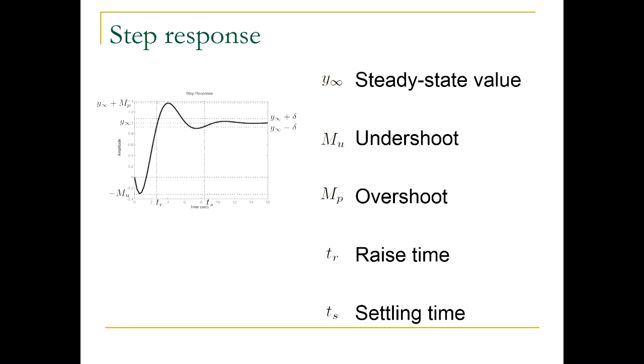So for settling time, very good question. Note that I denoted here y infinity plus delta and y infinity minus delta. Y infinity is the steady state value. That's where your response would converge. And then you're saying, well, let me look at maybe 1% up and down of the y infinity, or 5%. So settling time is related to this delta, how much margin you are interested in.